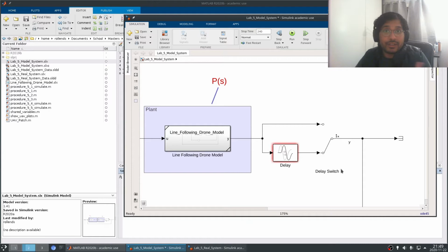Of course, if you design your system poorly, you might have a stable system when closed loop, when this path is going without the delay. But when you add the delay in and save the model, and you run the model linearizer tool, you might have it be unstable. So I'm just going to quickly show that as part of showing the last plot, the few things that we are going to do with the model linearizer. So let me just switch it to that and save.